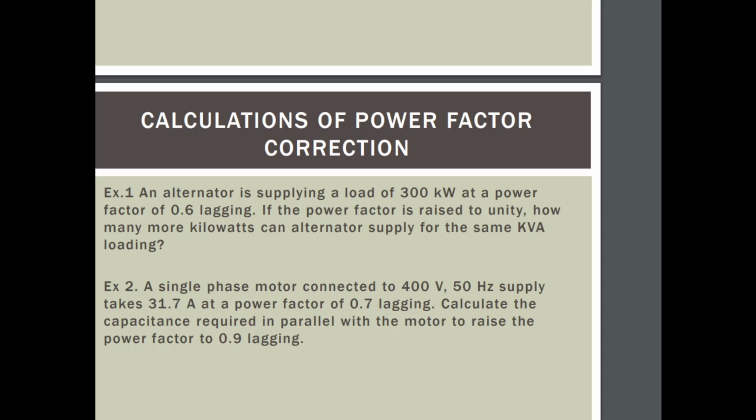So we have originally a triangle whose power factor is 0.7 lagging. Let's deal with that first. So if the initial power factor is 0.7, then what is the initial angle? So it's inverse cosine of 0.7. What's the inverse cosine of 0.7? It's 45.573.